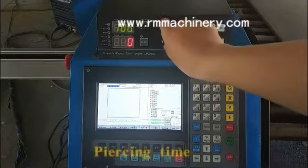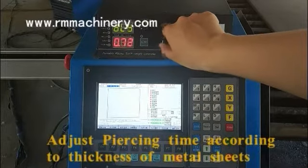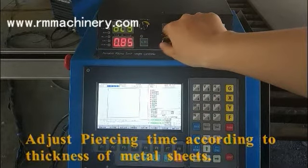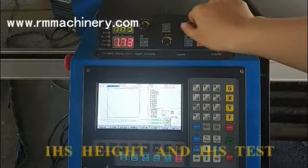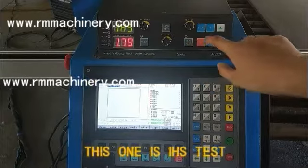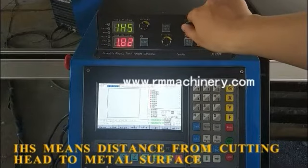Piercing time. Adjust piercing time according to thickness of metal sheets. IHS height and IHS test. This one is IHS test. IHS means distance from cutting head to metal surface.